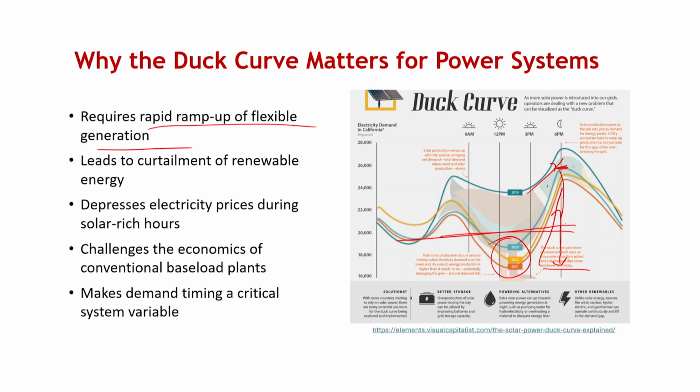It may also lead to a situation where electricity generation prices have to be drastically cut during this period of time, especially from renewable energy, because you want people to suddenly consume more, or you have excess generation and you cannot store electrons because you don't have that storage available. If you don't have that storage, then you may have to sell electricity at a very cheap rate during this phase, just to avoid tripping of the system from an excess generation perspective.